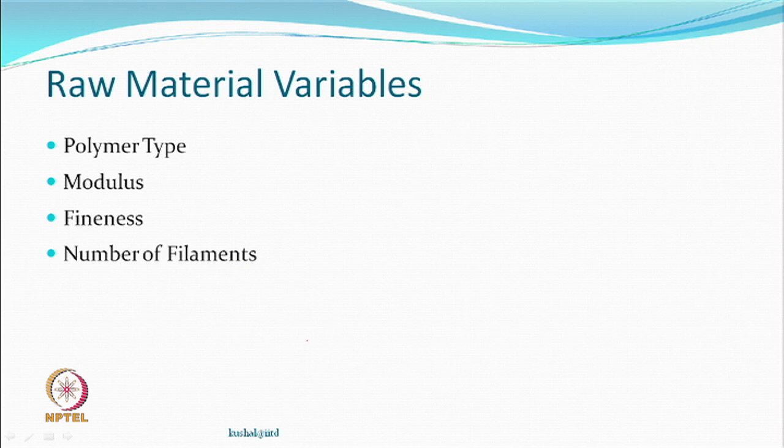This also became interesting, the number of filaments. It can be related to fineness. For the same total linear density, if the number of filaments is more, all of them have a probability of getting entangled, forming loops and increasing the bulk. So, the larger the number of filaments, the more likely you will get a better yarn.